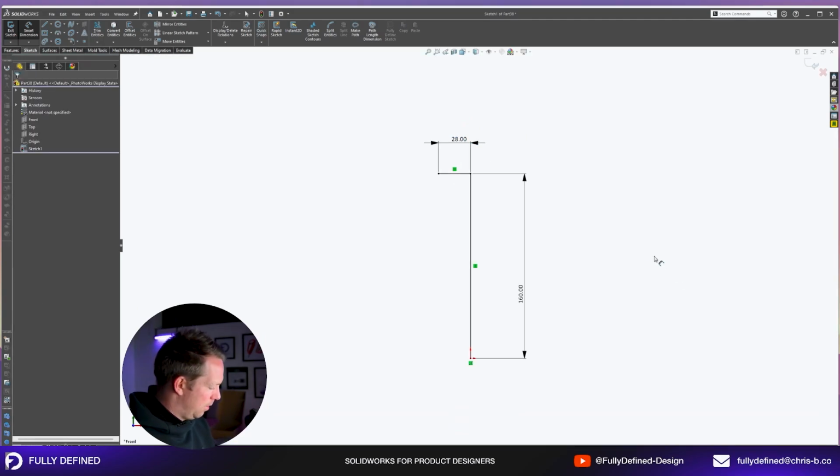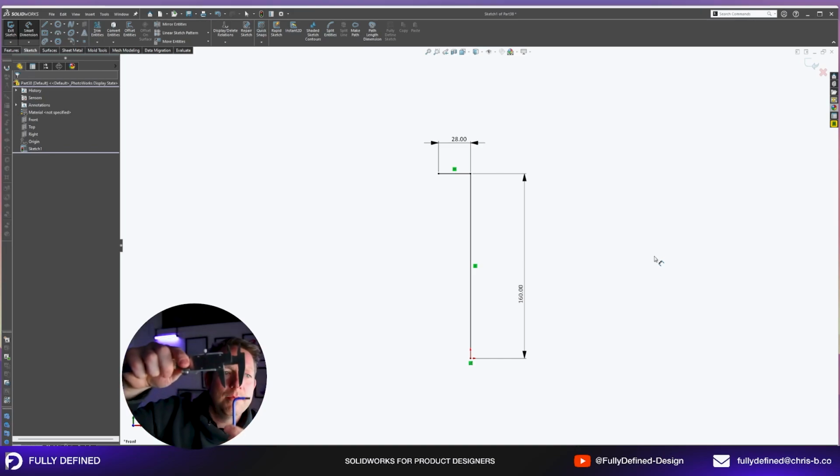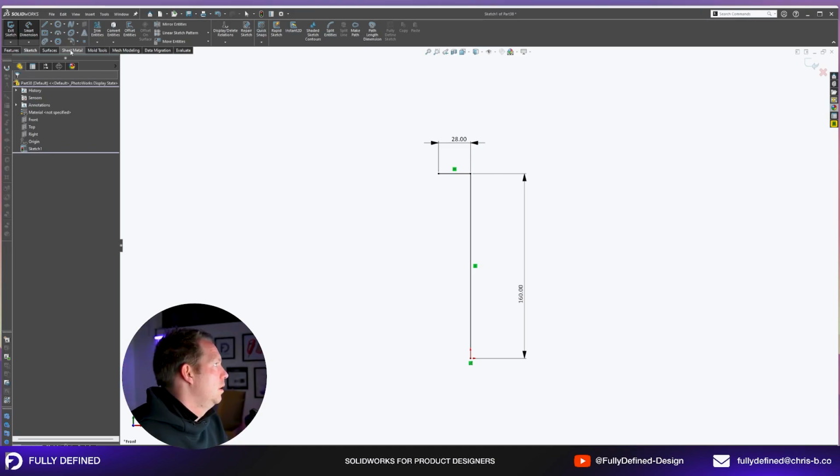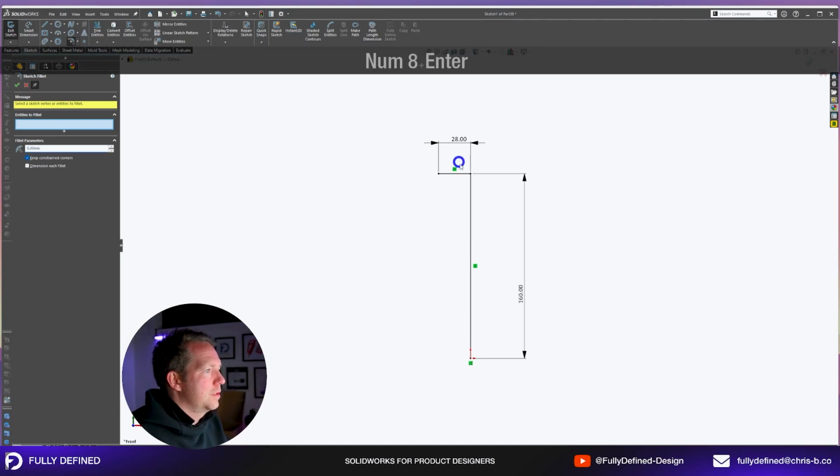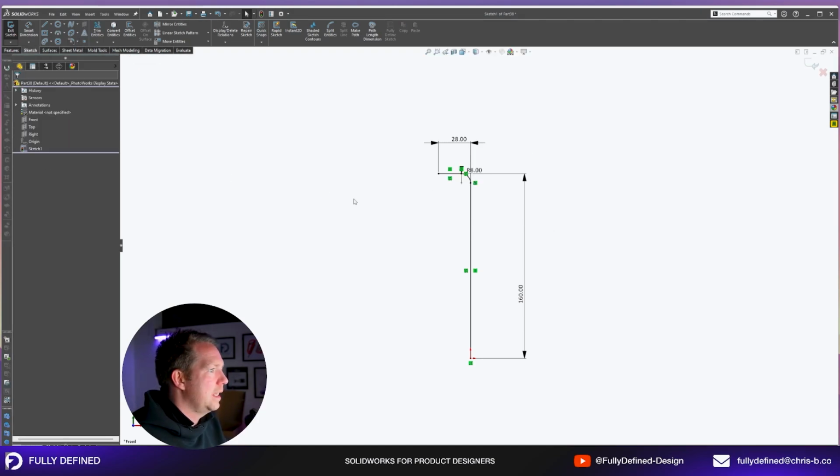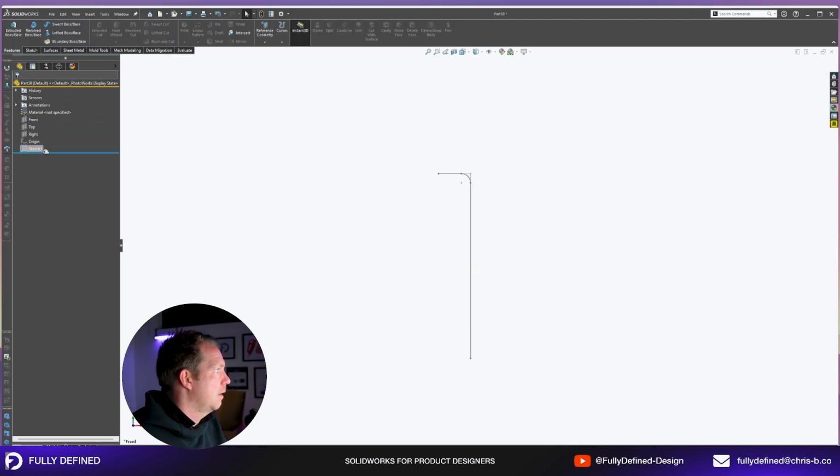Now, one thing that we don't know from these dimensions is the radius here. So I'm going to measure it. I'm going to use my calipers here, and I'm going to line them up with the center point of the hex, and I want to find where that radius turns into a flat, so where it's tangent with the straight edge. Now, it's not perfect, but it doesn't need to be. This is just a tutorial. I reckon it's around about 8 millimeters. Could be 9, could be 10. I'm just going to use 8. So I'm going to put a fillet in there for 8 millimeters.